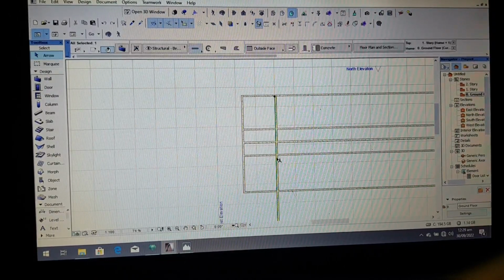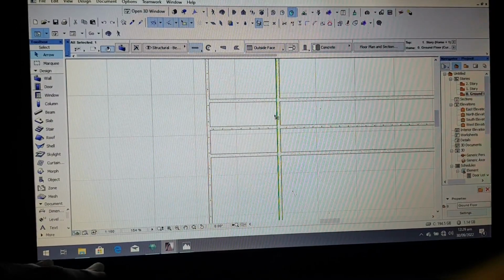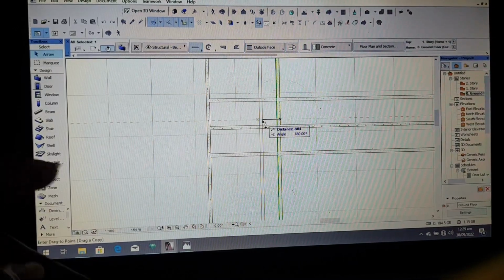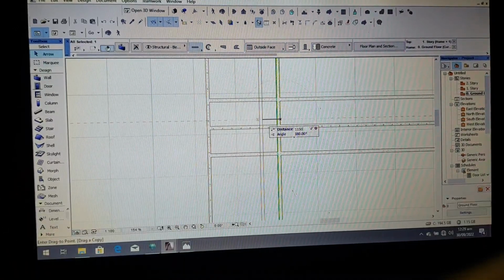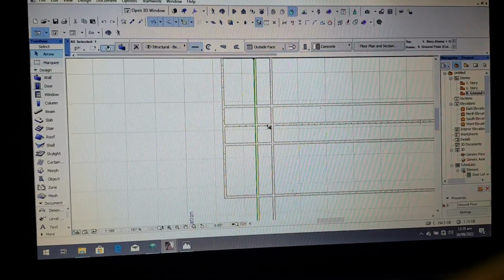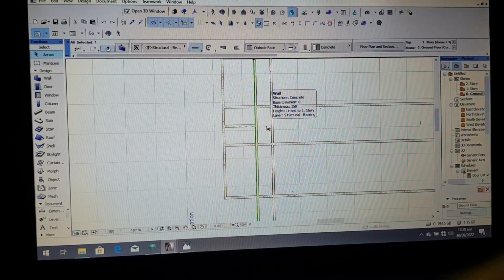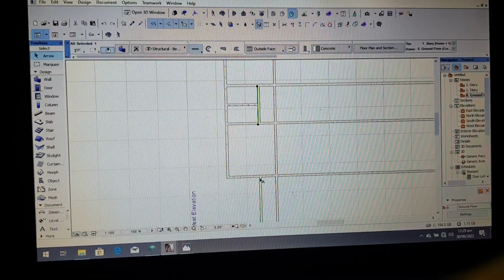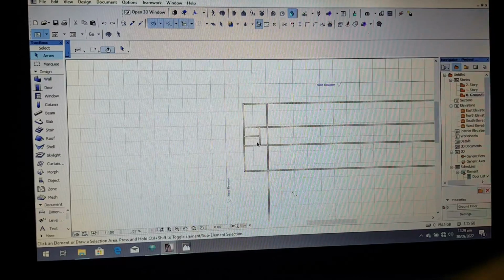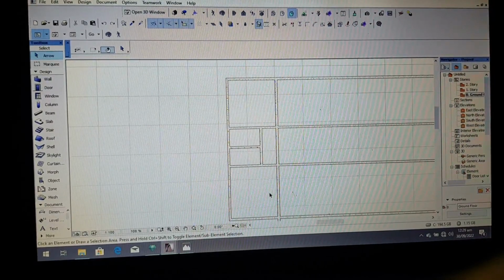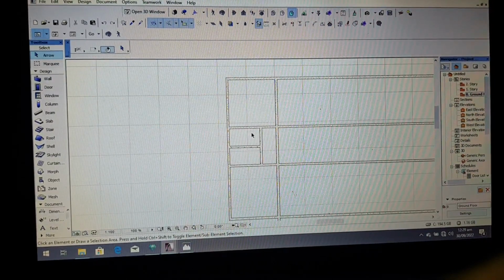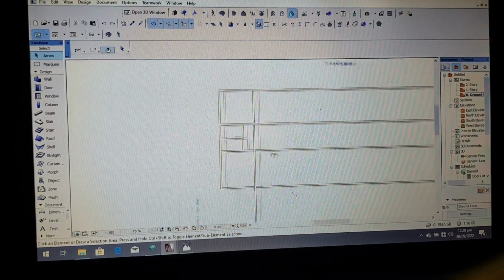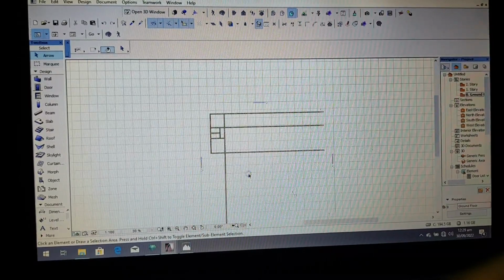Yeah. So let's create the lobby. This is the lobby. You click this wall, you press Control D and Control to copy. Lobby could be 1 meter, so we'll go for 1150. The 150 is the block thickness. You press Control, right click this, you take this off. You go here, you delete. You can see we now have the rooms. This one room, this 2 room, this is the lobby, this is the toilet, and this is the toilet for this room.